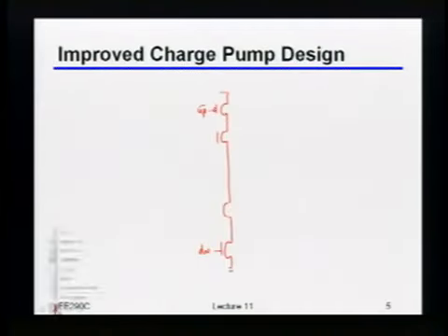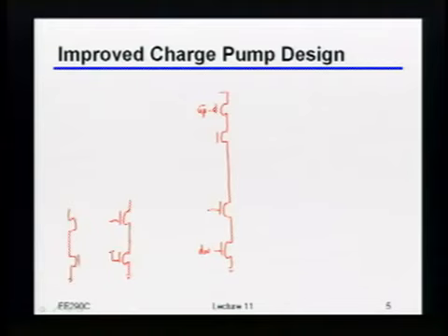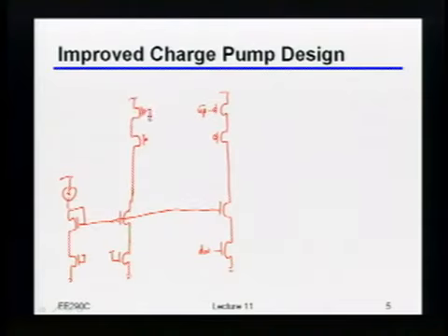Okay, so let's go ahead and see how we can do this. So this is going to be some bias voltage, and that's just going to again come from some mirror. So I'll draw that whole thing just for the sake of completeness. Okay, so I will indeed go ahead and do that. But now for this PMOS branch, how do I basically force those to have the same voltage? What do I do?